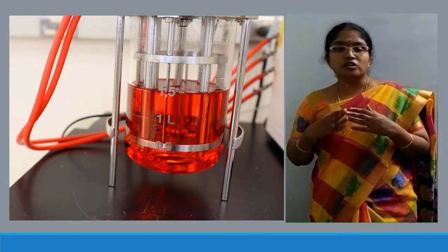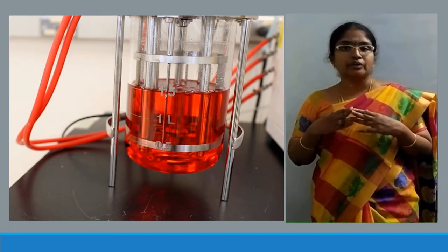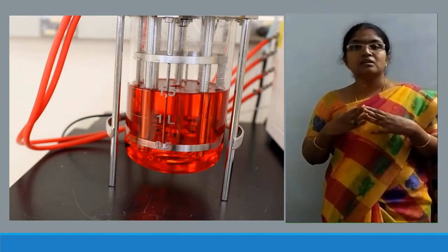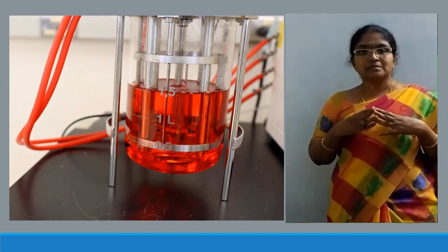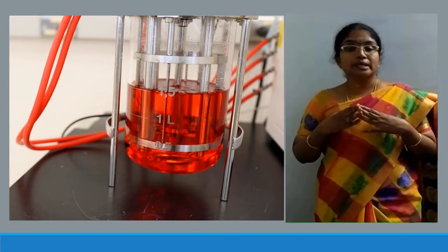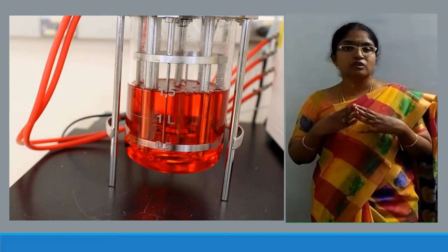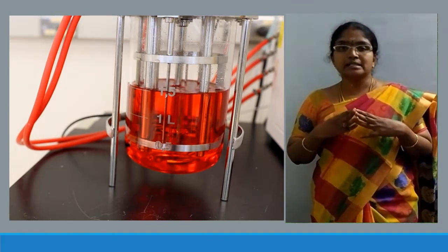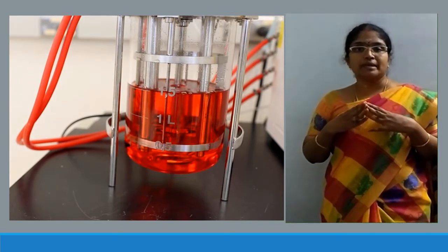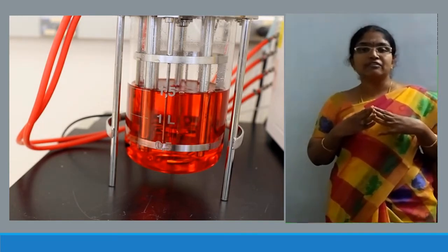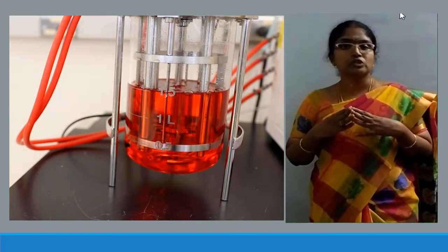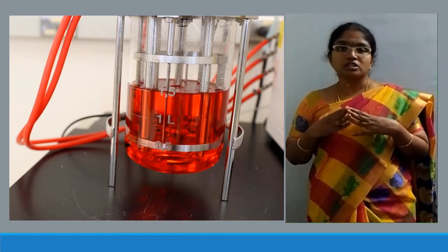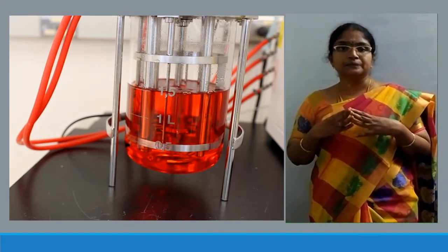And as oxygen is one of the limiting elements supporting the growth of organisms, it is mandatory to estimate the overall mass transfer coefficient of oxygen through the bioprocess. Hence, in today's class, we will be discussing in detail the different methods that are used to estimate the overall mass transfer coefficient of oxygen in a given reactor.